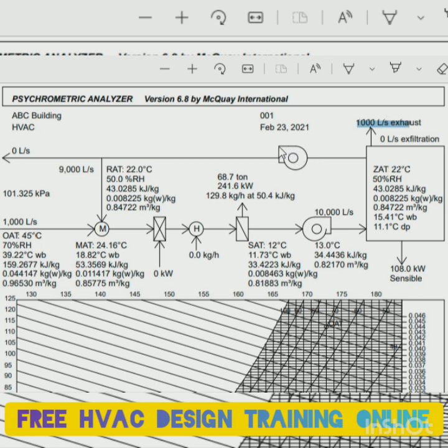Then the return side is not an actual fan, this is just a symbol. This is not a fan. It shows that air is returning back to the mixing plenum box of the air handling unit. Then after the mixing chamber, we have a pre-filter and the final filter, and after that a heating coil. This is your humidifier, because we did this calculation only for the summer, not for the winter. So that's why we have a load only on the cooling coil.